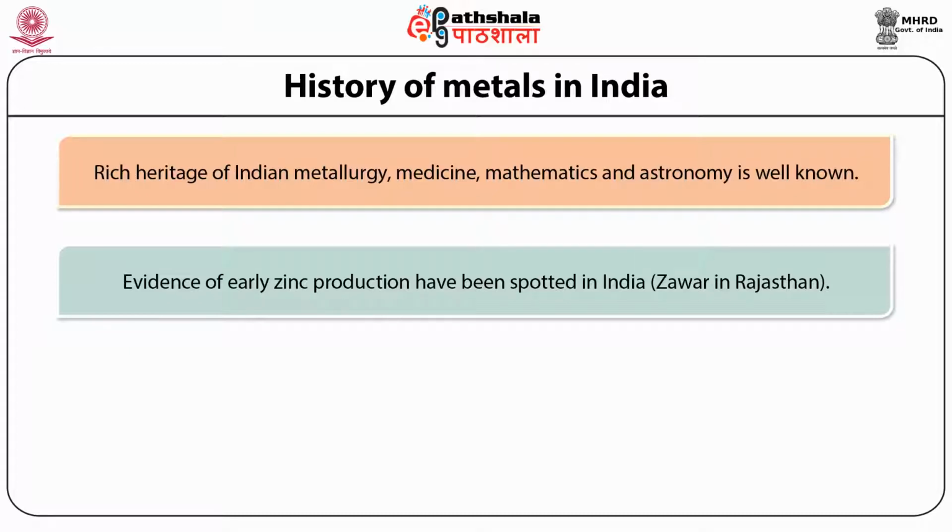An interesting method was designed where downward distillation of the zinc formed after smelting zinc ore was carried out using specially designed retorts with condensers and furnaces, so that the smelted zinc vapor could cool down and form a molten pool of zinc metal which could later be solidified.